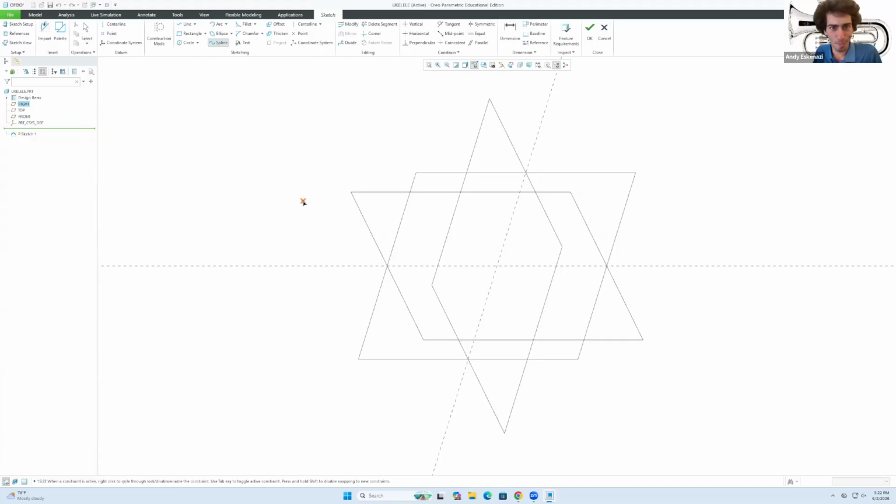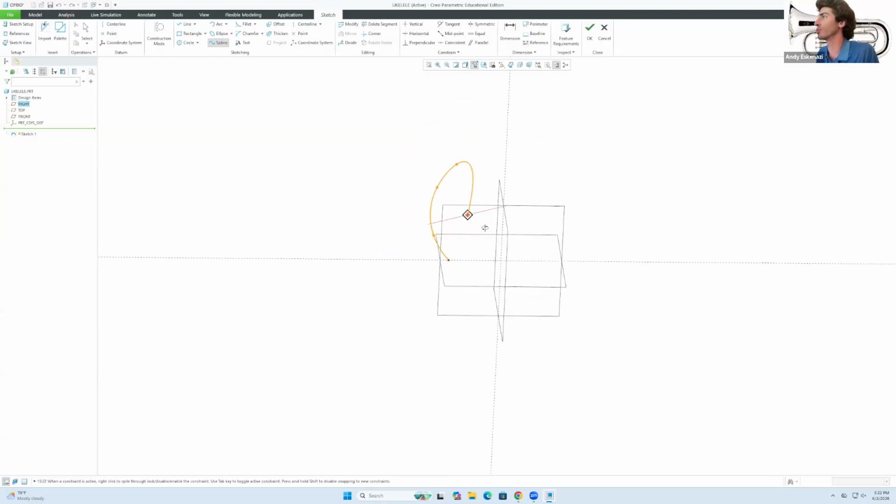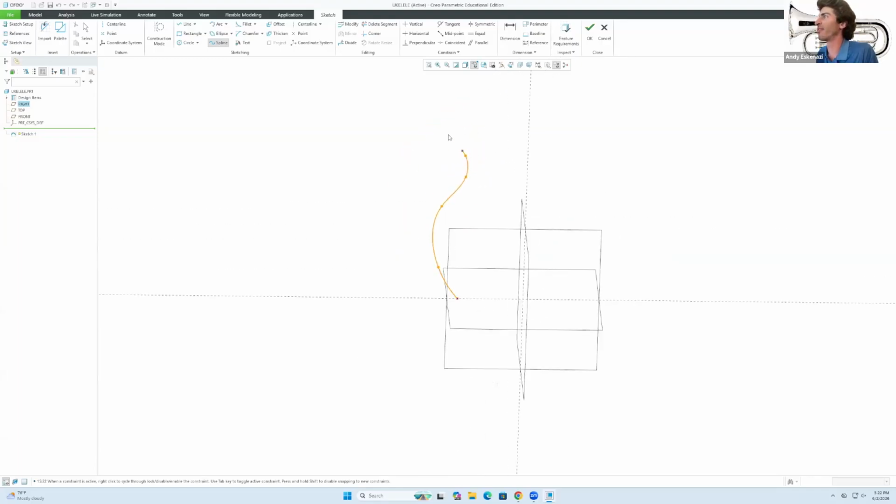What does spline do? It's super simple. It's almost like tracing little points around a drawing, and you have essentially formed a curve. For instance, I can click in here, then go there, and so on. Let me just zoom out and make a funny looking shape. I'll go all the way like that. Once I'm happy with the curve I've arrived at, I click the middle button of the mouse, and voila, we made a spline.